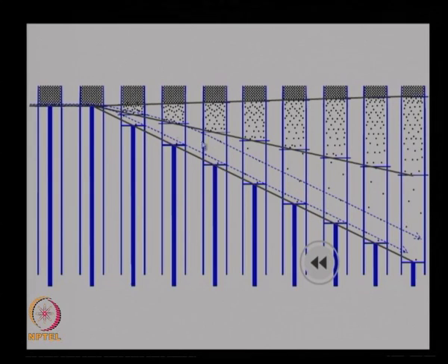And what you are seeing is that this particular particle you are tracking is here, and it is now here, now here, like that. If you are tracking that particular particle, that is the lower streamline, it is coming here, it starts to turn somewhere around here where the first expansion line touches it. After that it changes, and then it comes to a constant rate, it is becoming parallel, it is moving parallel to the wall.